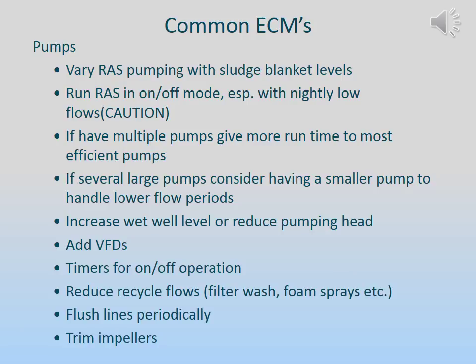We can especially do this at nighttime when flows are low to start with and we are typically slowing down the pump considerably. If we have multiple pumps, give more runtime to the most efficient pump. Or if there are large pumps, consider having a smaller pump to handle the lower flow periods. Increase the wet well level or reduce pumping head, and if you can, add VFDs. Again, not as something that is going to necessarily have to pay for itself, but we can do it as an upgrade.